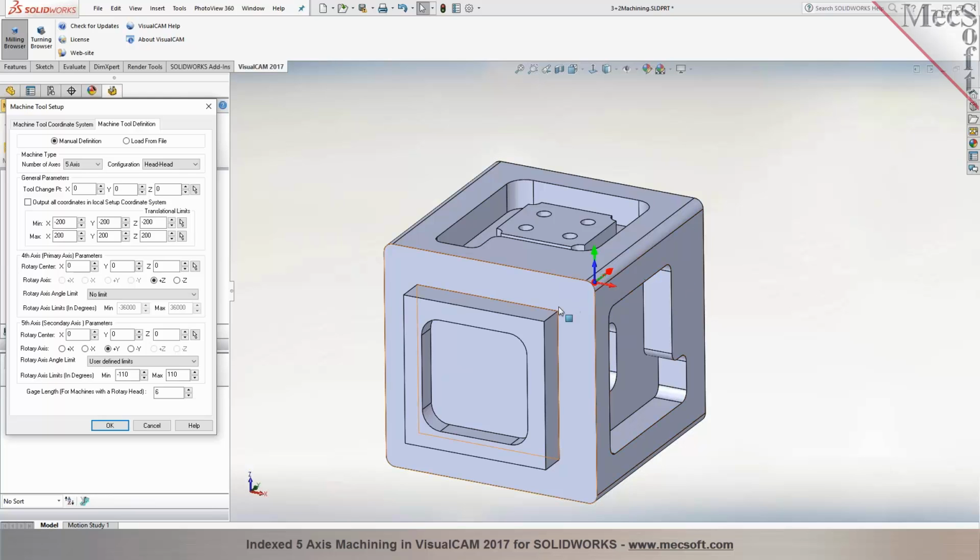So in this particular case, if you're milling this face, your cutter is moving in and out along the y-axis. If you're cutting on this face, your cutter is moving in and out along the x-axis when you look at it down from the top, looking down from the world coordinate system orientation. So unchecking this box will transform this Z motion into the motion that is in the world coordinate system.